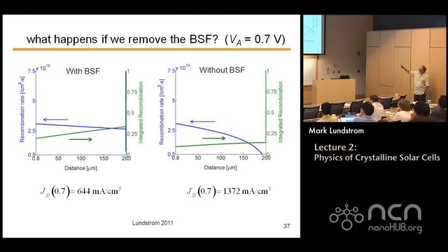If you look at that green line and you see the big jump it takes at the end of the device, it goes from 30% total recombination and then it jumps up to 100%. So 70% of the recombination is occurring at that back contact, and the back surface field is not keeping them away. If you look without the back surface field, it's even worse. There it looks like it's probably 85% of the recombination is occurring back there. And your total current, meaning your total recombination, is significantly higher. Okay.